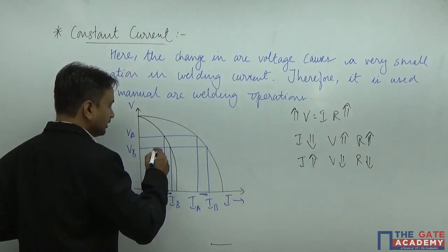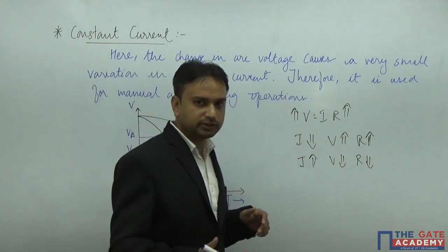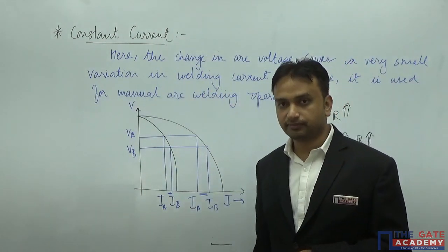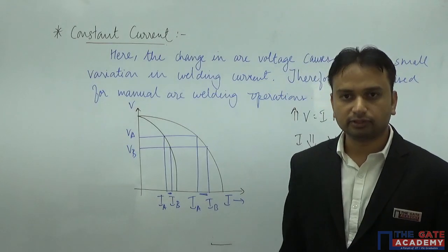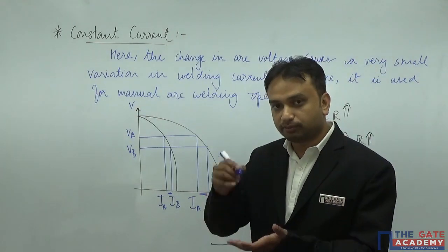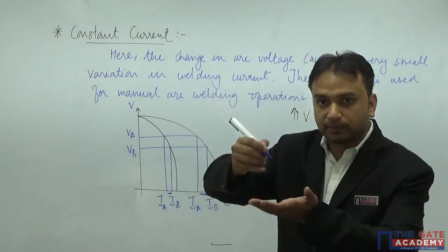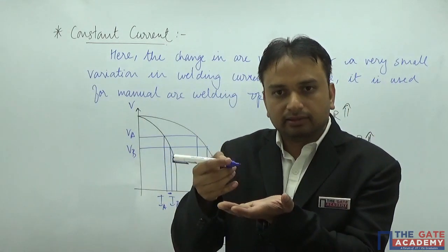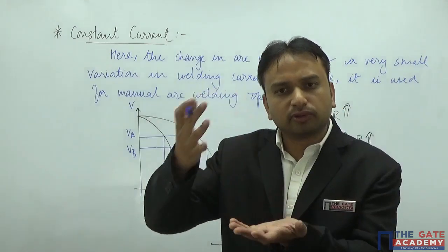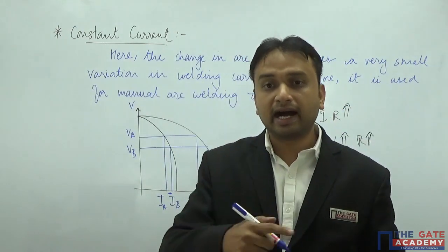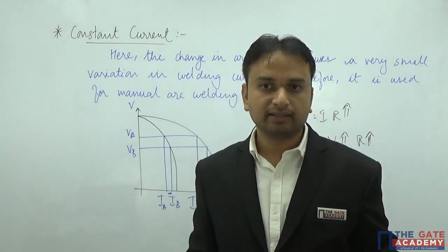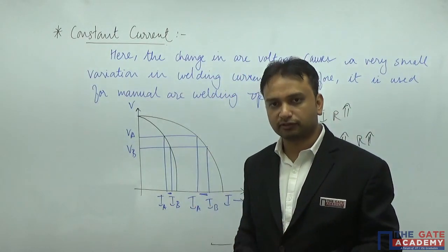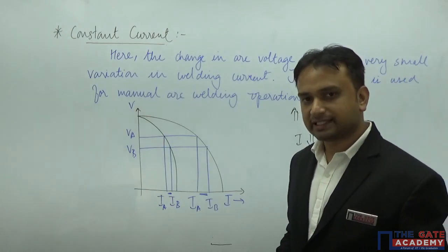So that means the second power source that you saw in the shop was the best one. You purchase that, and whenever you are performing the welding operation, even though my hand shakes, the length is going to change, and the voltage is going to change in turn, but I is not changing much. There is no variation in the current. I hope that you have understood. Sufficient explanation has been given to you.